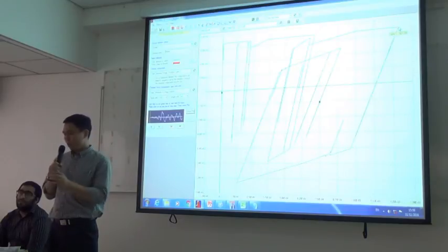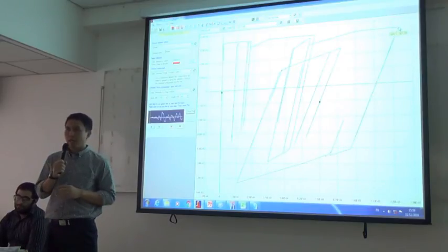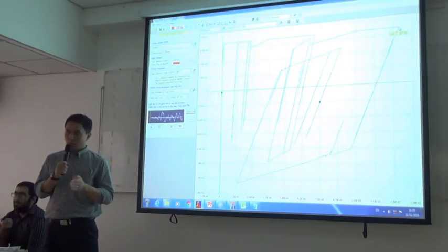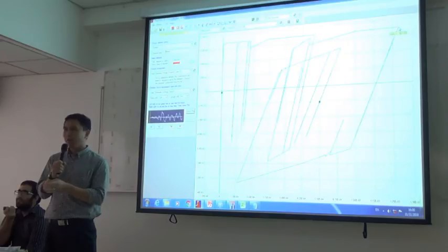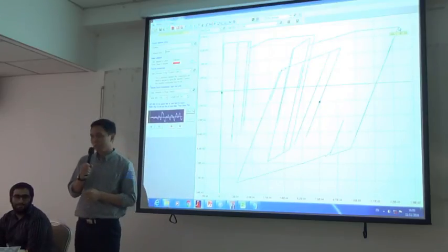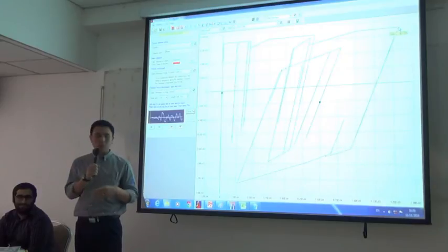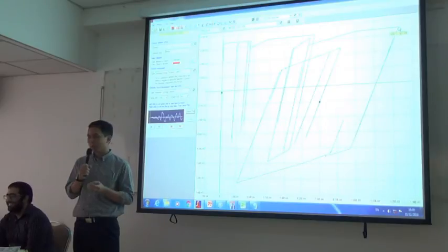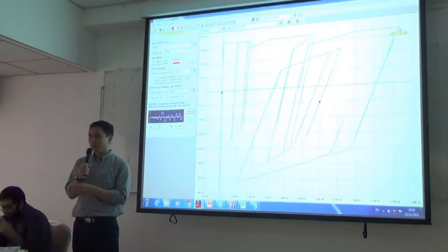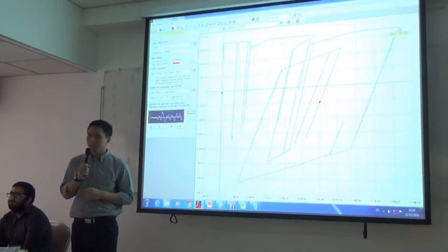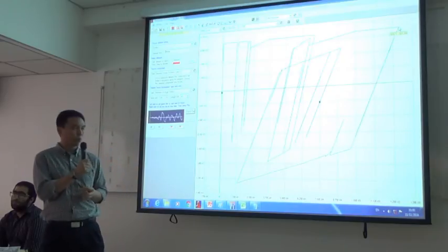We have to do this for 7 ground motions, and then we post-process the results. For example, for shear wall shear, we have 7 sets of shear wall shear, and then average them. Then we multiply it with a 1.5 factor. Then we check the shear reinforcement. Same thing for the other components. But for the rotations, we just need to extract the rotation values, with no need to multiply with the factor. Then average it and check the rotation limits based on the ASCE 41 criteria.